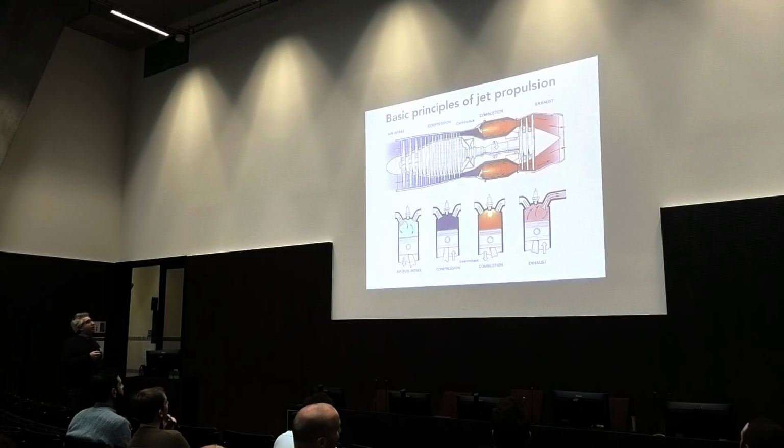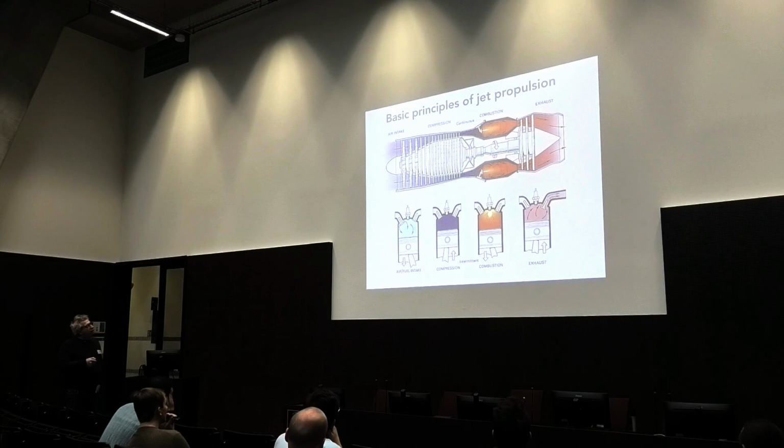All right. What's inside a jet propulsion engine? Typically, that is a very simple configuration where you have a compressor that will compress the inlet air. Then when the air is at a very high pressure, typically 50 times that of the inlet, you enter this air into a combustion chamber that will raise the temperature to a very high temperature, typically 1500, 1600 degrees.